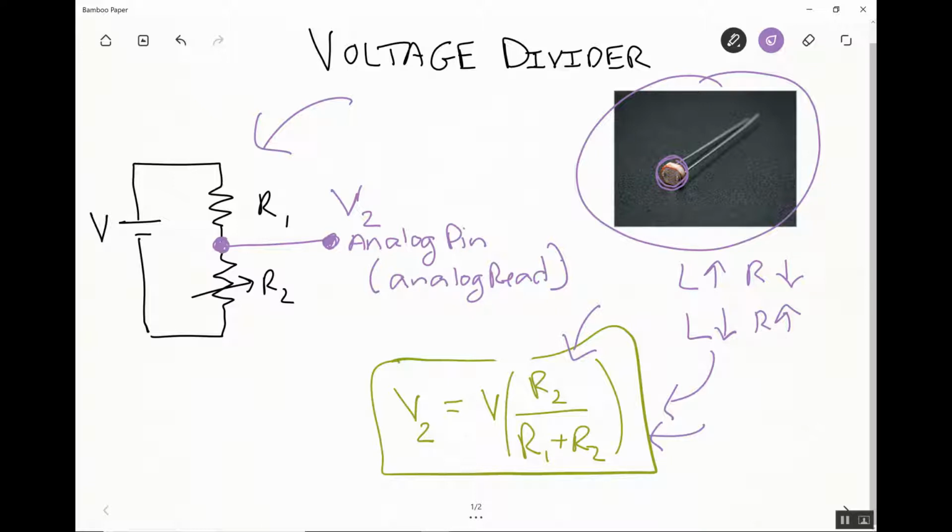All right, so those are two examples of applications of voltage divider circuits for hooking up an analog sensor, in this case, the photocell sensor. In class, we used an analog sensor, the temperature sensor, and whether you realize it or not, we hooked that up in a way that set up a voltage divider circuit, and we measured the voltage being used by the temperature sensor. We also looked at the example of a voltage divider circuit in the context of designing a circuit to make an LED work with the proper voltage and current so it lights up, but it doesn't burn out.